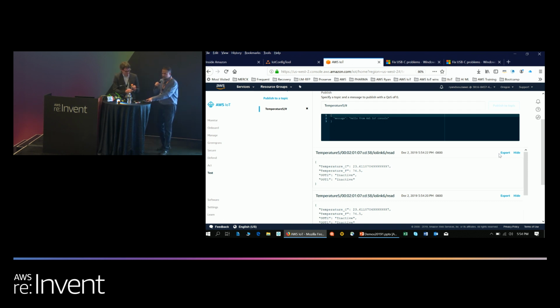Yeah, so what we have just done is added a temperature sensor to the CloudRail box. It was automatically detected. In addition to the automatic detection, what also happened is that it automatically provisioned the certificates and the security needed for the device to connect to the AWS cloud. So all that happened automatically behind the scenes in terms of getting an X.509 certificate, putting it onto the device. The temperature sensor is then able to authenticate with AWS IoT and start publishing messages.